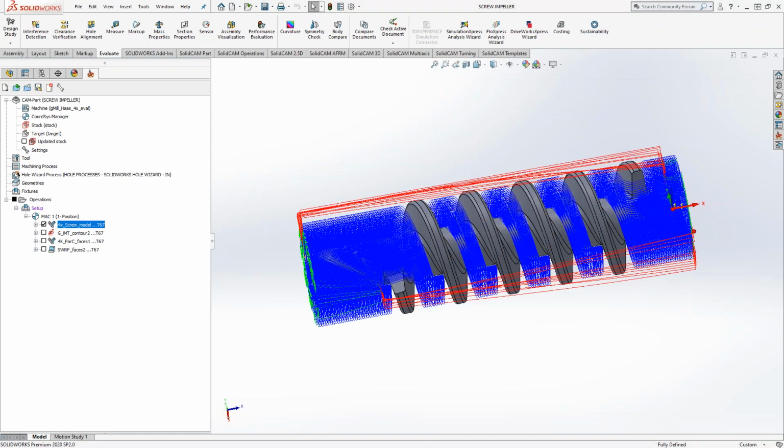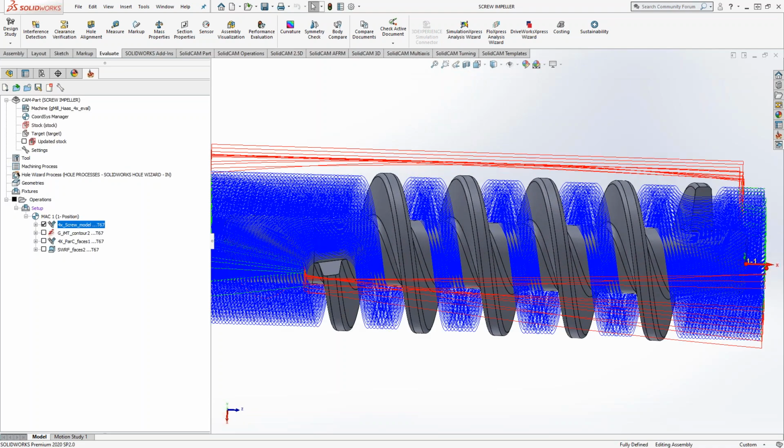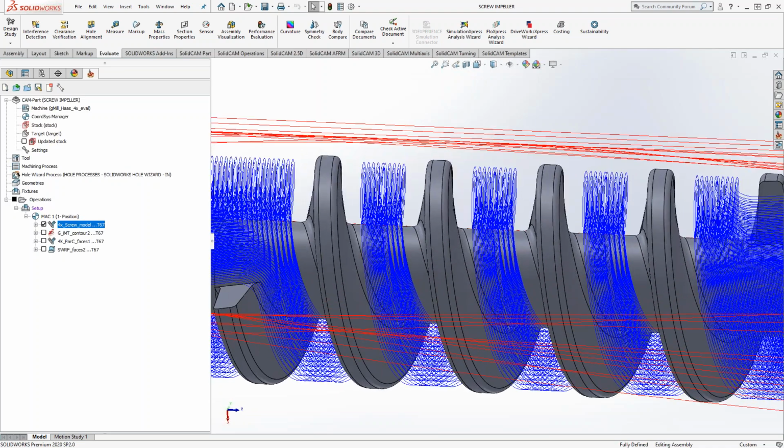This is the screw machining toolpath we were talking about yesterday. As a review, the screw machining toolpath is not for a screw machine, like a Swiss screw machine. It's just the idea that it will follow the patterns of your part. It's developed for these feed screw impellers, this helical shape, but you can really use this for any 4th axis part.